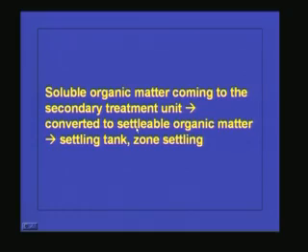If you take the aeration tank alone, we cannot call it a treatment system because what is happening is only the nature of the solid is getting converted from the soluble form to colloidal form. So, if you want to get the removal of the solids, we have to have the sedimentation tank. So, the secondary sedimentation tank is an integral part of the activated sludge process.